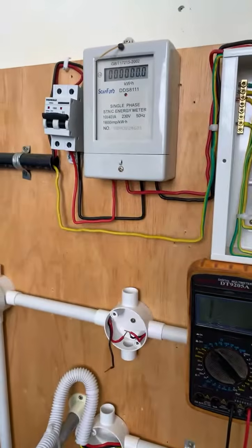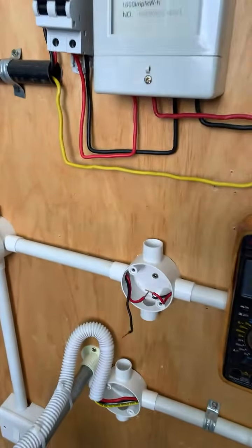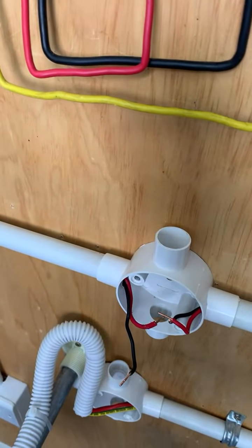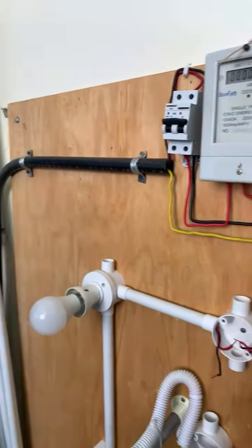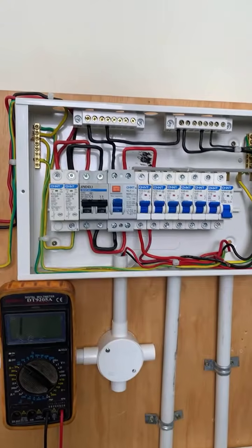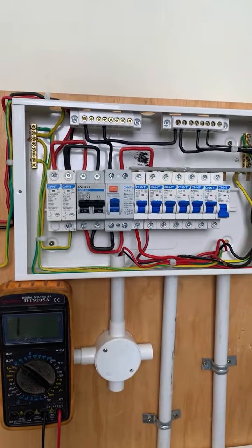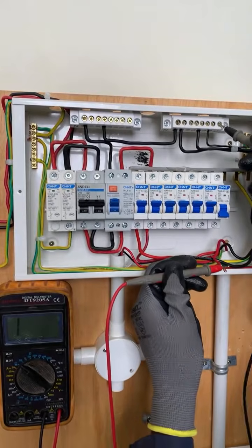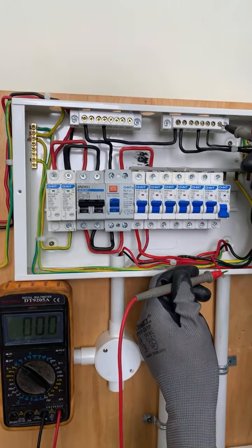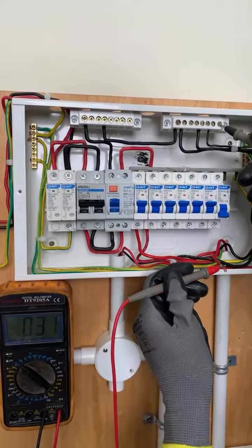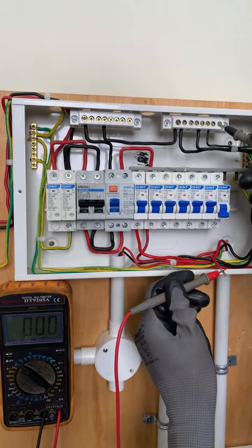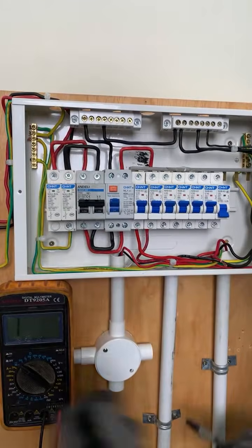So this is a makeshift problem. Does that make sense? So the neutral and the line, or the neutral and the phase, have clashed right there on the circuit of our light. So the MCB right there is down, or it has tripped. What we expect is a short circuit between the line and the neutral. So if we connect here and here, there we go. We have the beeping sound. We have zeros on the meter as opposed to very high resistance. So that is the problem that is here.